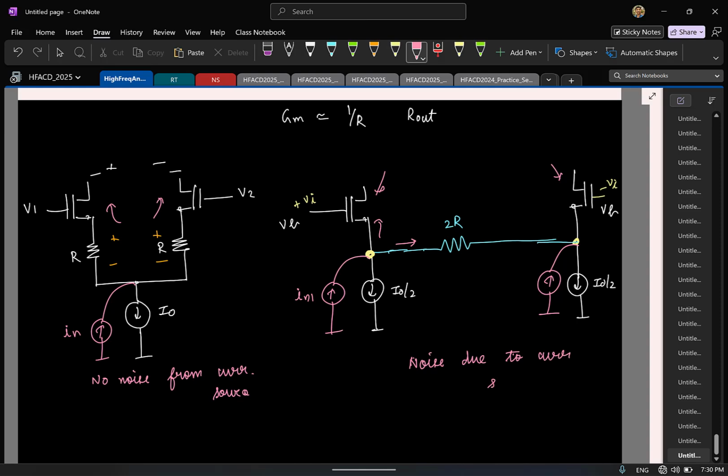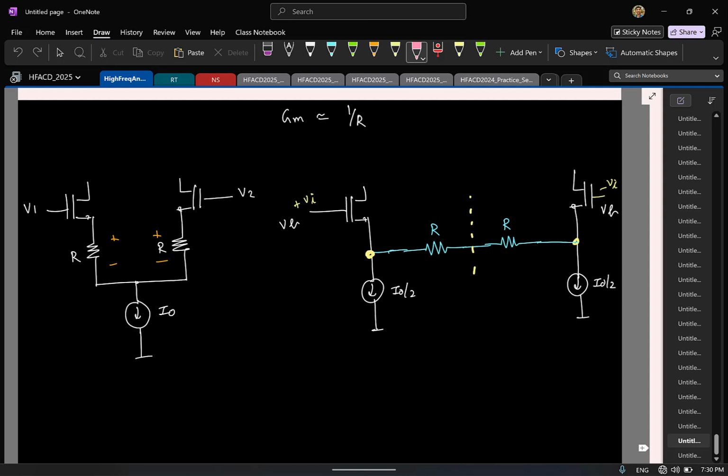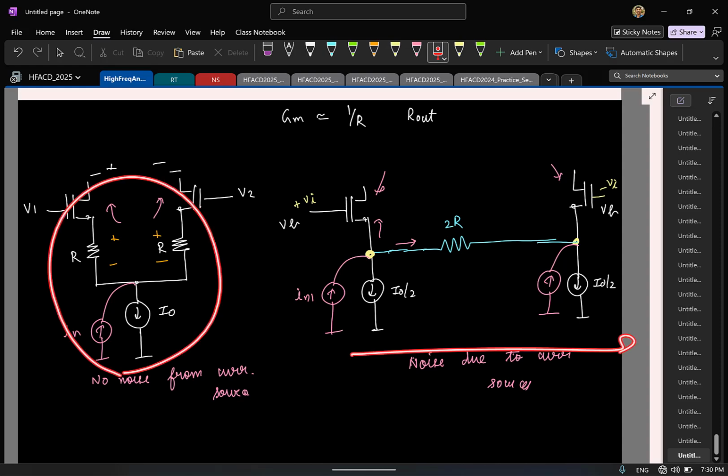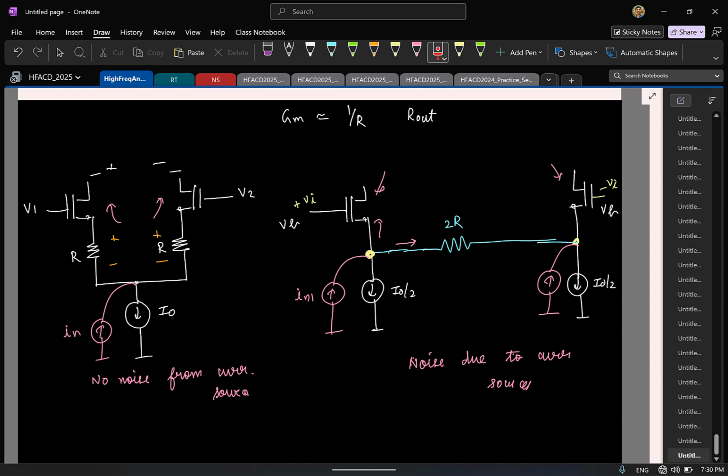Still, right, doesn't matter. Even if you had the capacitor, the same thing, right? For small signal, the capacitor is shorted, right? Noise is small signal. Okay, this is one common trick that is often done. Either you do this or do this, and again each has its own pro and con. So depending on the situation, you sort of use it.